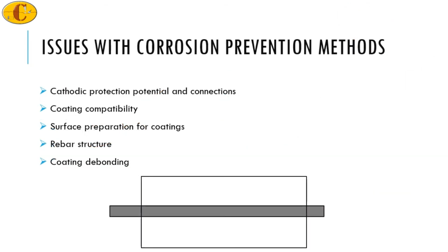The issues, if it is cathodic protection, may be the potential measurement and the connections. If the connections are not good enough, or if the connections are made internally and there is a small breakage, it is not possible to detect it at the moment it is broken. Only when the protection is lost completely and there is some indication outside may the connections be checked, or sometimes it is not really possible to check the connections at all. This usually affects the protection potential.